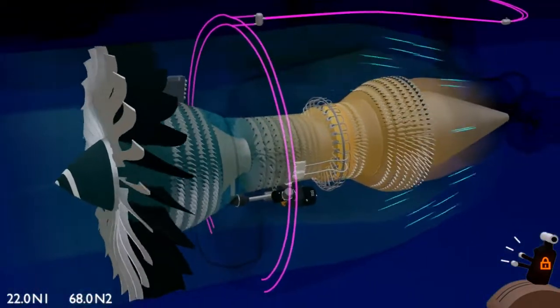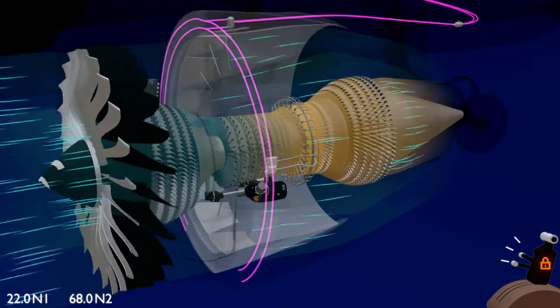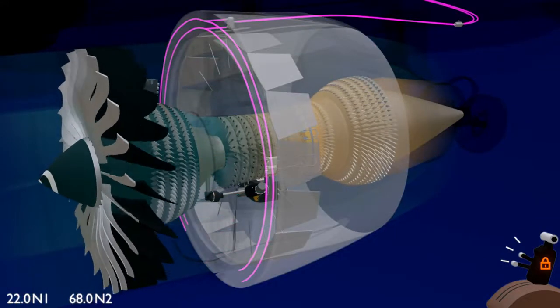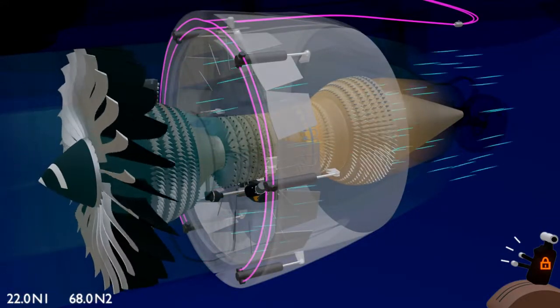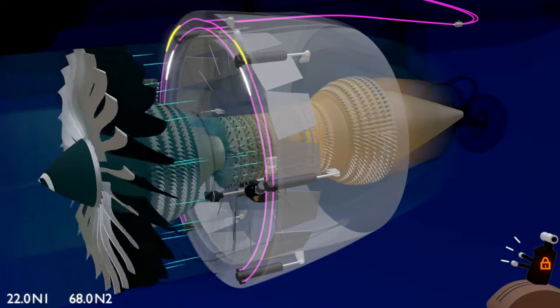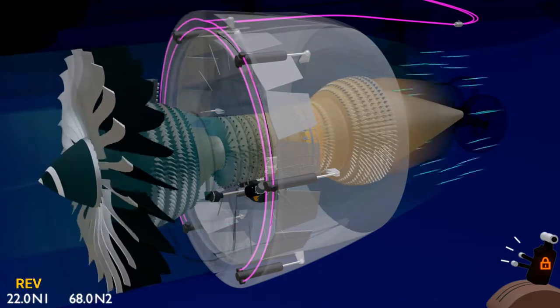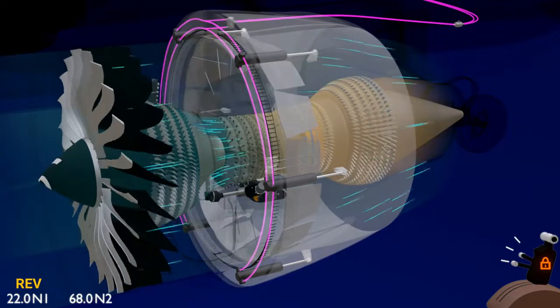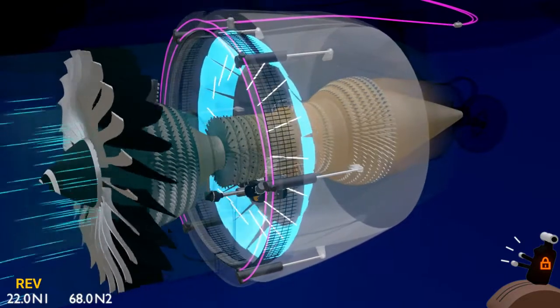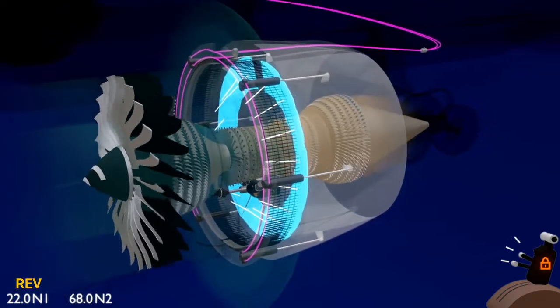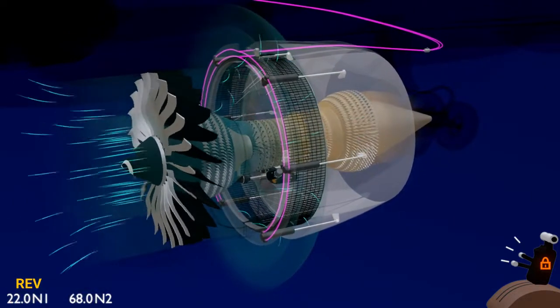The engine thrust reverser is a combination of two halves, and each half has 3 actuators. The DCV applies pressure to the extend side of the 6 actuators. The actuators extend to move the reverser sleeve to the aft. Connected to the reverser sleeve are the blocker doors that get dragged with the sleeve and move to the closed position.